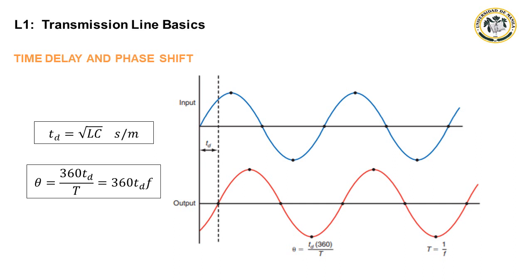Transmission line delay is usually ignored in RF applications, and it is virtually irrelevant in radio communication. However, in high-frequency applications where timing is important, transmission line delay can be significant. Some applications require exact timing and sequencing of signals, especially pulses. A coaxial delay line can be used for this purpose.